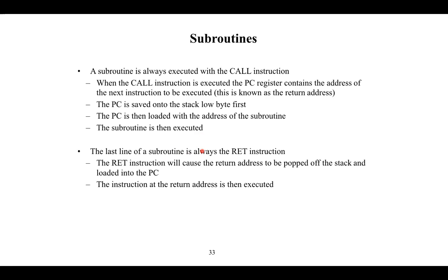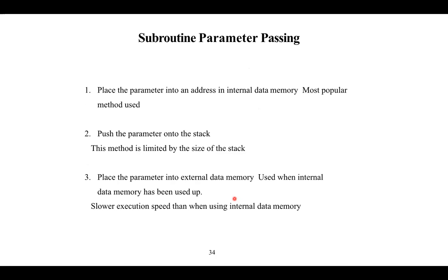The subroutine is then executed. The last line of the subroutine is always a return instruction. The return instruction will cause the return address to be popped off the stack and loaded onto the PC. The instruction at the return address is then executed. Subroutine parameter passing.